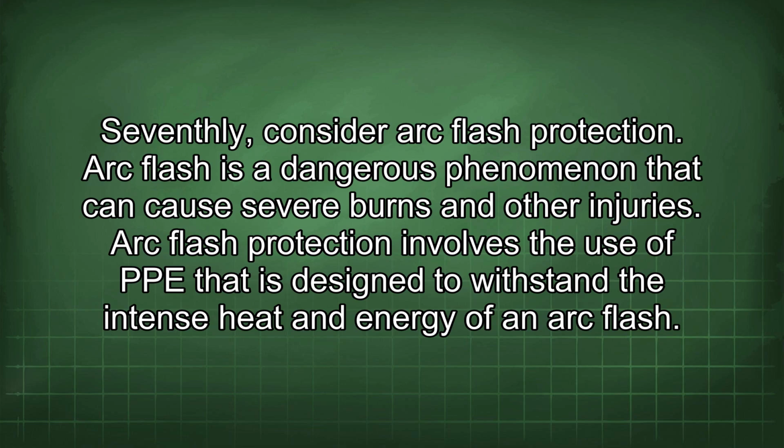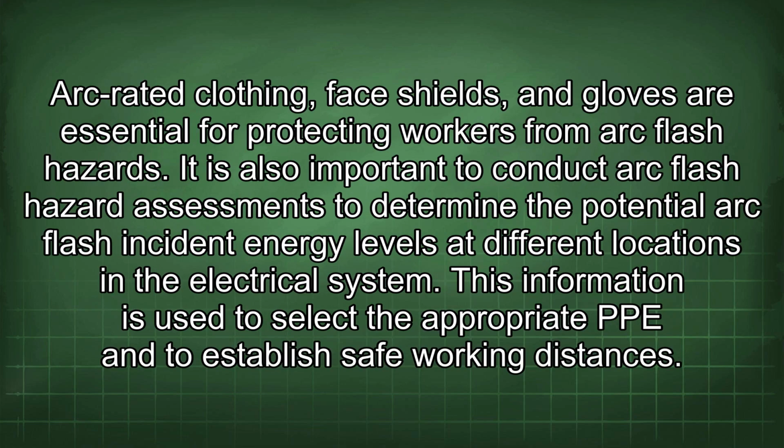Seventhly, consider arc flash protection. Arc flash is a dangerous phenomenon that can cause severe burns and other injuries. Arc flash protection involves the use of PPE that is designed to withstand the intense heat and energy of an arc flash. Arc-rated clothing, face shields, and gloves are essential for protecting workers from arc flash hazards. It is also important to conduct arc flash hazard assessments to determine the potential arc flash incident energy levels at different locations in the electrical system. This information is used to select the appropriate PPE and to establish safe working distances.